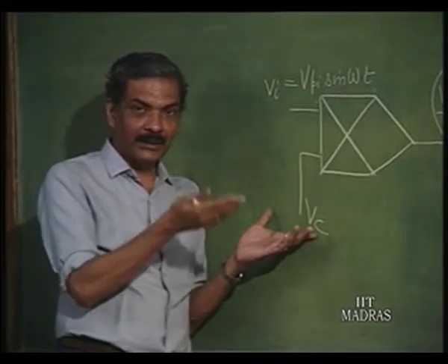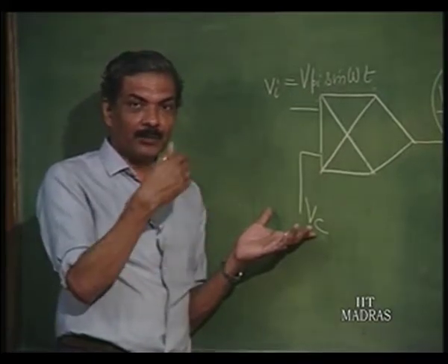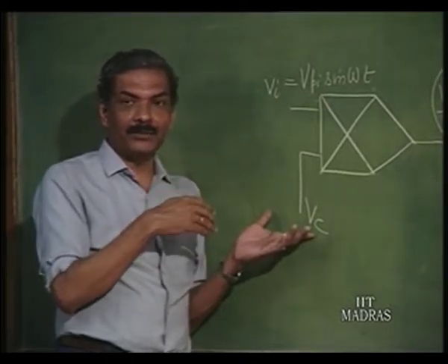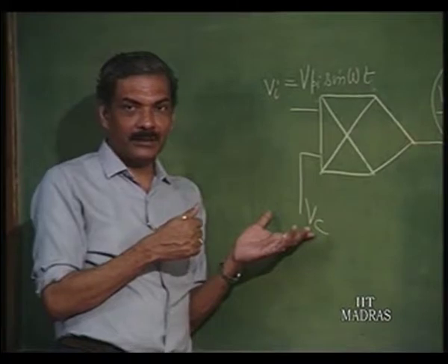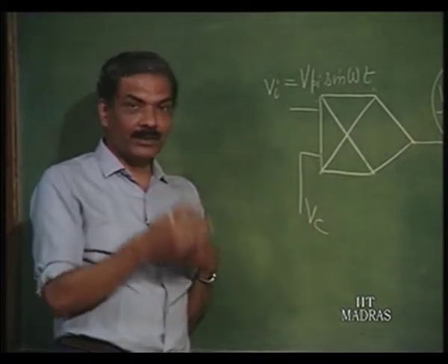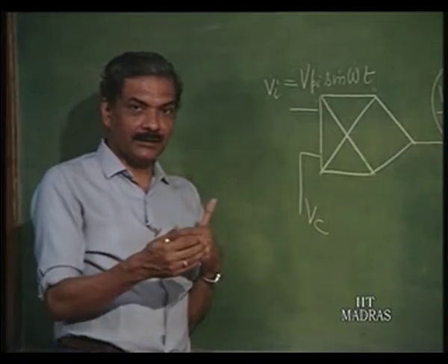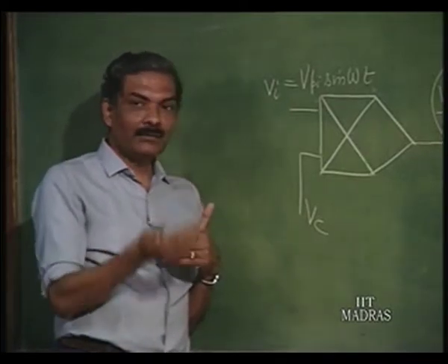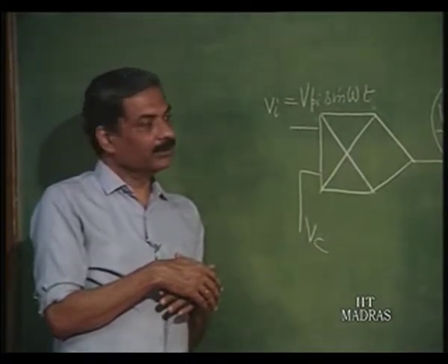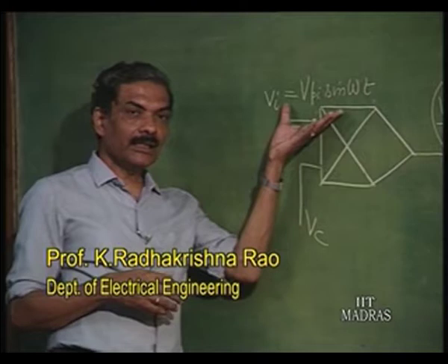The DC information that is outputted at the detector is directly dependent upon the amplitude of the IF received. Okay. So, how do we receive this DC information? We have to convert the AC into DC. So, for that we have to have a rectifier diode arrangement. So, we will discuss that also. Essentially, there are 2 points.